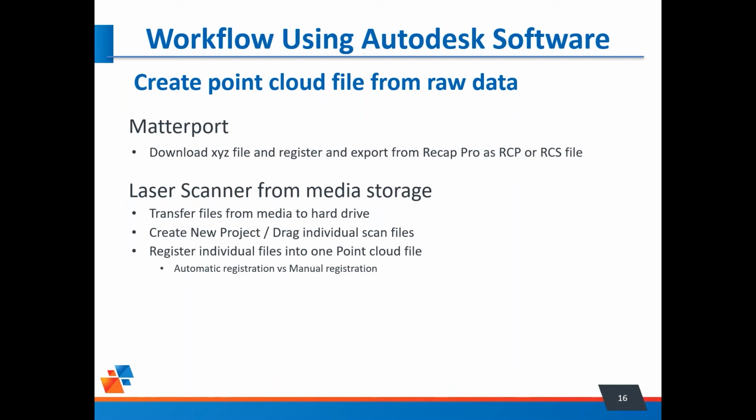Basically, all that really means is we take individual scans, save them as individual files, and then when we put them together inside Recap, we decide whether we want the software to do it automatically, in which case we may have wanted to use spheres or targets when we do the scan.